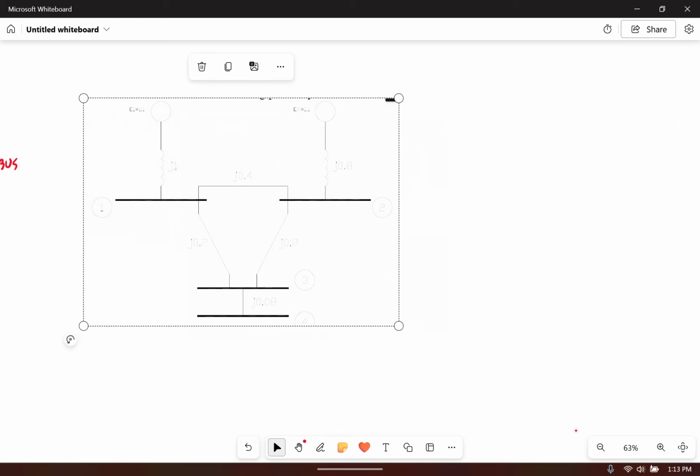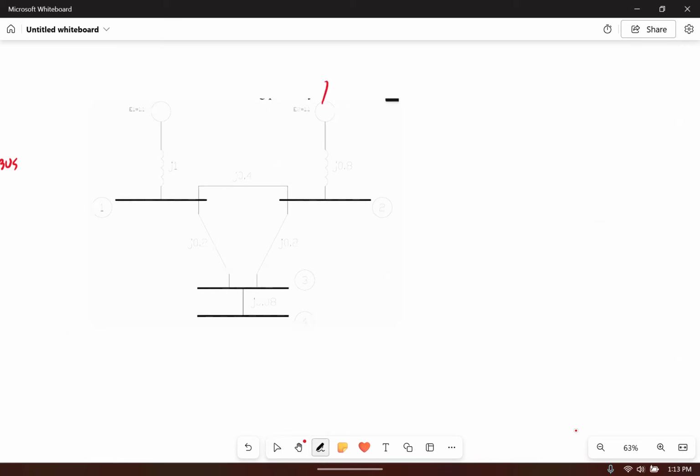And again, you don't actually have to show the reference because it's a 3-phase system. The reference bus of the system is the other 2 phases, right? So I don't actually have to show any connection over there. In the real world, how a generator is connected, you have 3 lines that go in and then back out of the generator. At the generator, at the neutral connection, they're tied together. So there isn't necessarily a connection to ground. Usually there is a connection to ground, but the reference is right here.